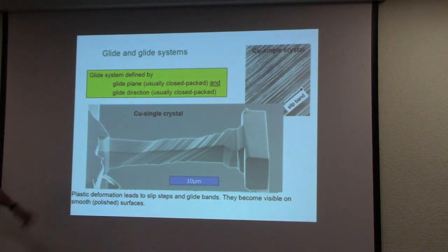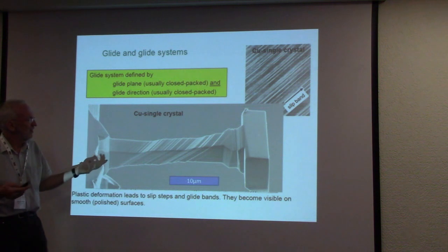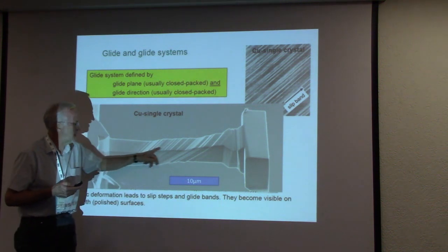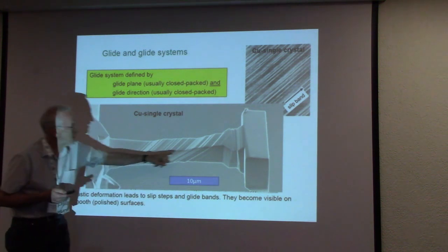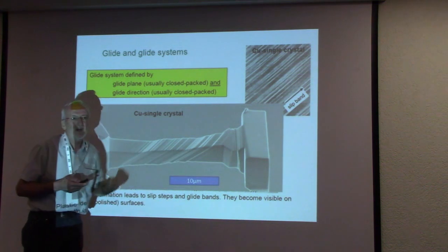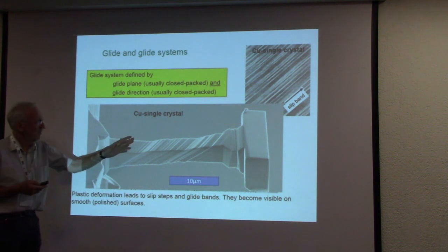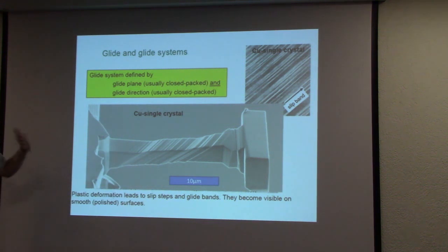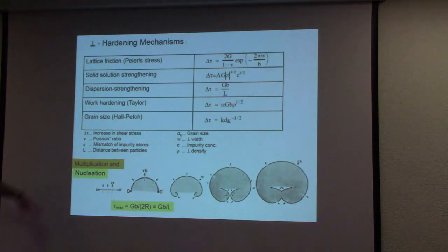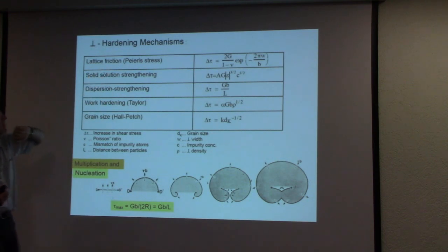And so if you apply continuum mechanics, you can apply it only on this scale, but it makes no sense to apply the stress-strain behavior on a scale which is smaller than typical distances between the slip planes, or where dislocations are activated. I will not go through this. Important is there exists a certain stress to move the dislocation. This is the Peierls stress.